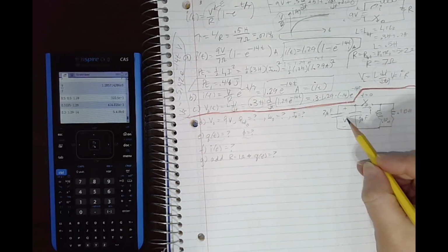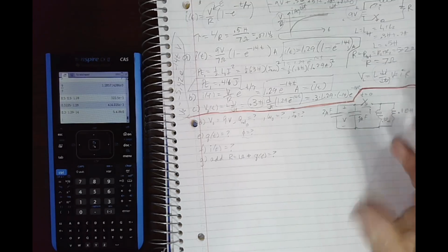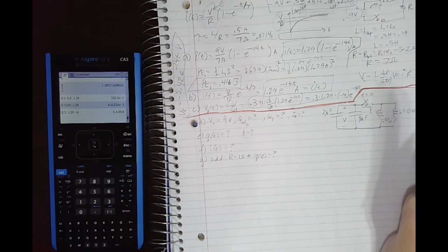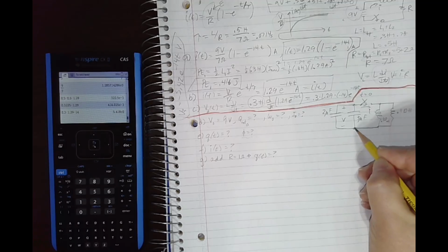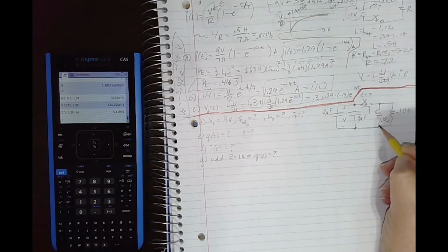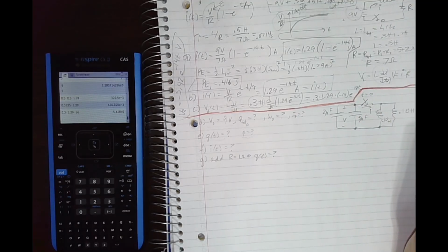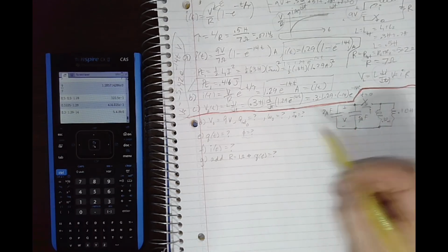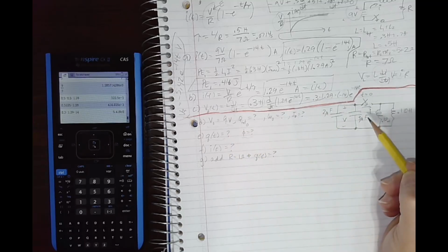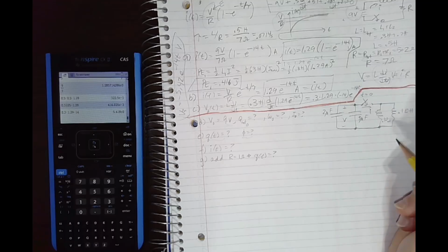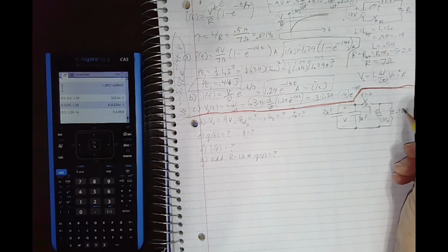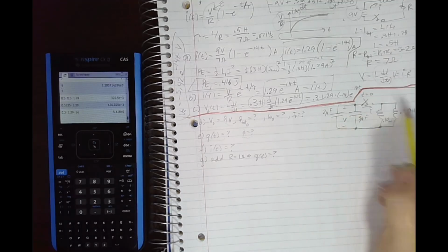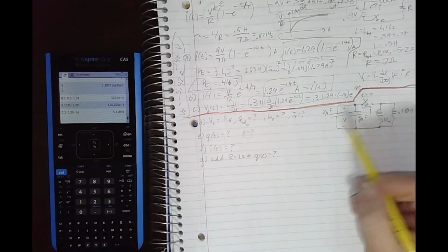So we've got a circuit here. This is an LC circuit, and these are assumed to be ideal elements, so they don't have any resistance, so they don't have any loss of energy. So if the capacitors are charged up when we start, then we close the switch, so they're going to have some energy stored in them, and we'll assume the inductors don't have any energy stored in them. And then when we close the switch, capacitors are going to give energy to the inductors, but then the inductors are going to pass it back again.